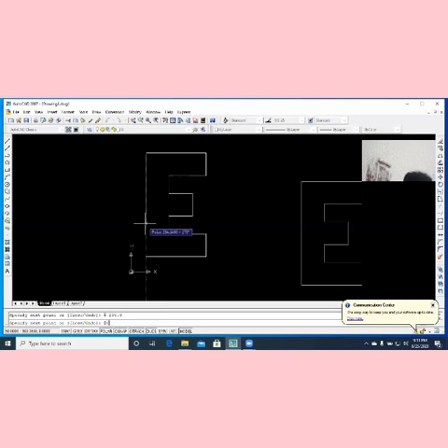And then Shift Alt 0, minus 345, enter. And that closes it. That's the last line. You press escape. You can see the shape, and that's using the what? Using the rectangular coordinate method. We'll now go to the last method, which is the relative polar coordinate method.